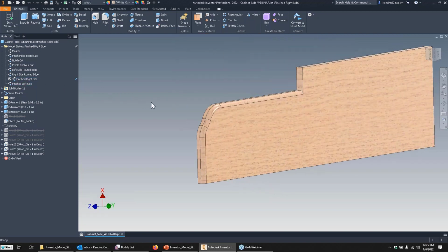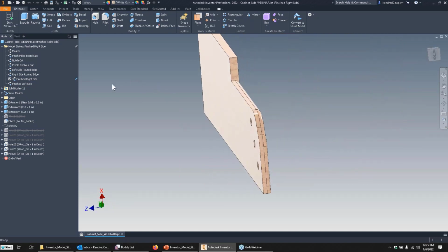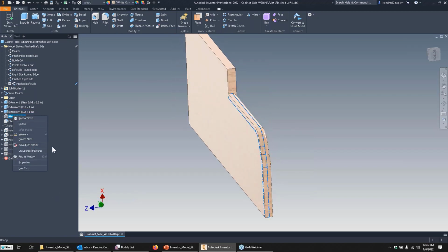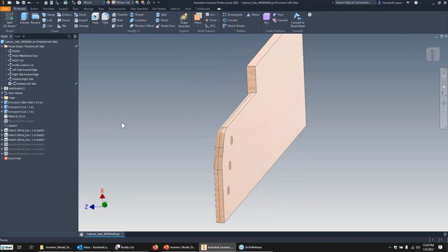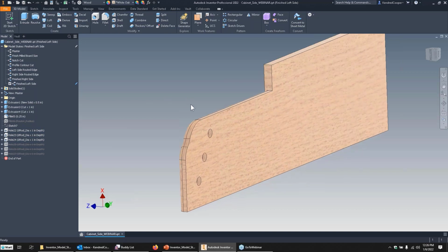So looking at the right side, we've got the drilled holes or countersunk holes on the outside. They're turned off. That's how it should be. If I switch to the left side, then I can unsuppress the 3 holes on the outside, suppress the 3 holes on the inside of this, and then flip my fillets. And this is what Keith was talking about. I could have gone to the other one and I wouldn't have to come over here and unsuppress this fillet and suppress the other fillet. It would already have the appropriate fillet suppression. So that would save some time, but I at least wanted to show you the flexibility that you could still go in and modify and continue unsuppressing other features.